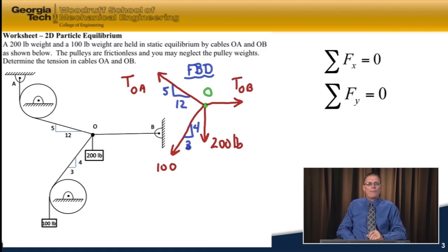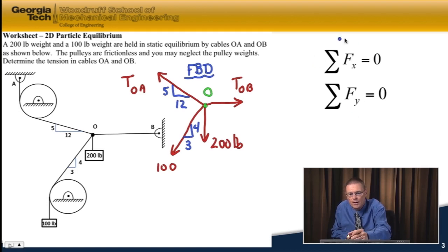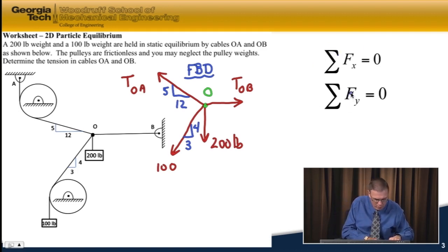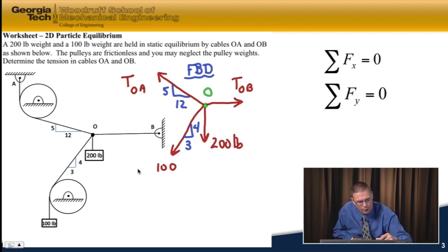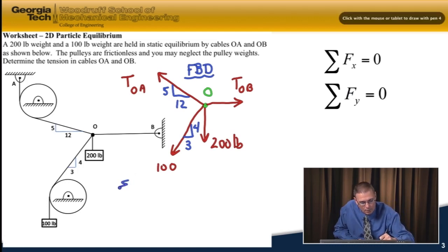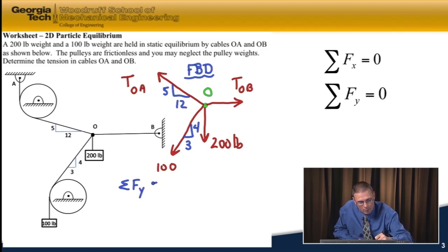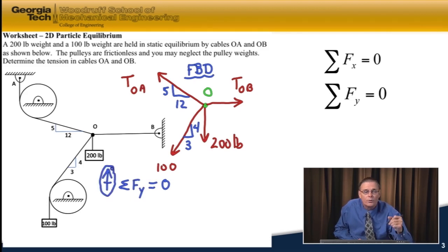Once I have that good graphical tool, that free body diagram, I can now apply my equations of equilibrium. I can apply them in either order. They're independent equations, so I could do some of the forces in the x first or some of the forces in the y first. This time I'll go ahead and choose to do some of the forces in the y direction first. Equals 0. And for assembling my equation, I'll assume up is positive. I could assume down is positive. You may want to do that on your own to see that you get the same answer.